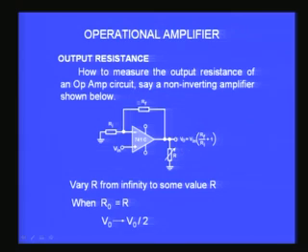So, what we do is we just take one typical amplifier configuration. You can see on the screen, it is a non-inverting amplifier. You have the RF and the R1, and the R1 is grounded here, and the input is applied at the non-inverting input, and the output we all know, V output is equal to V in into 1 plus RF by R1. This is the gain factor. So, now this is a very simple non-inverting amplifier about which we have already discussed.